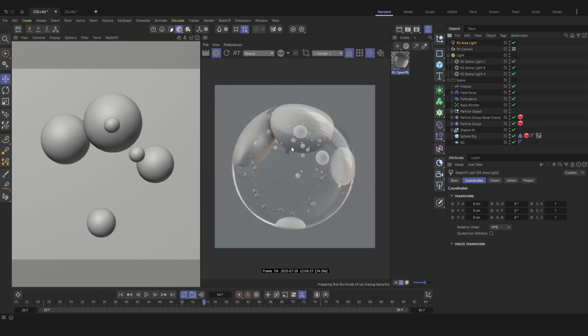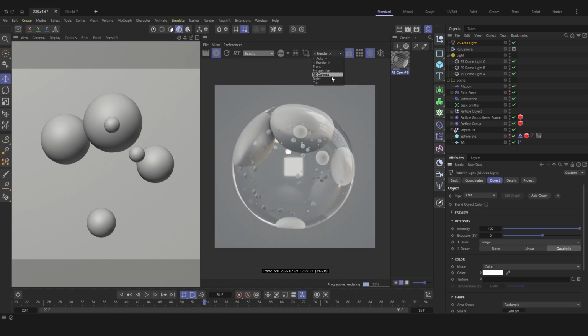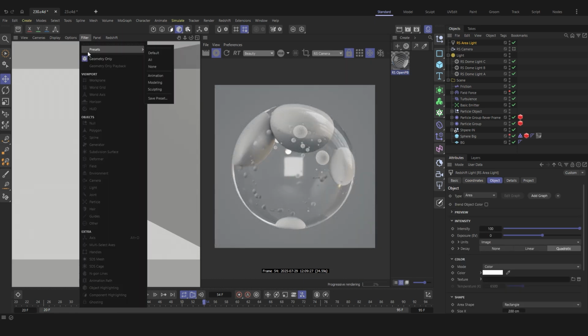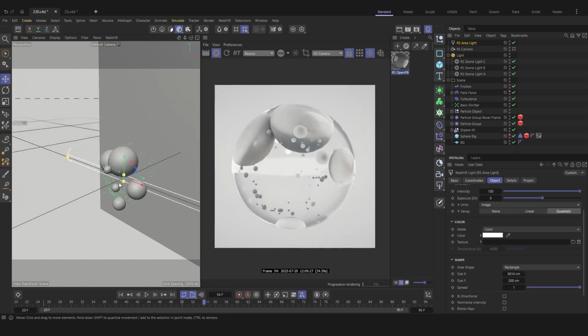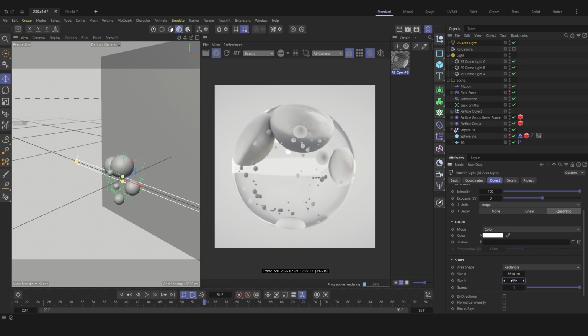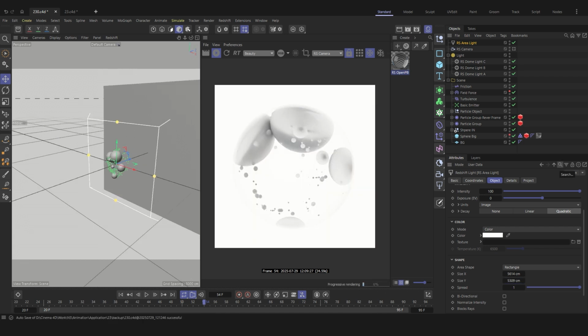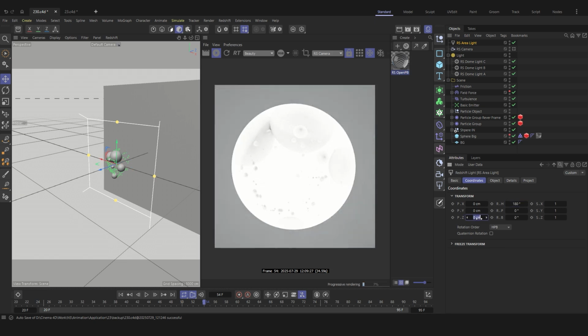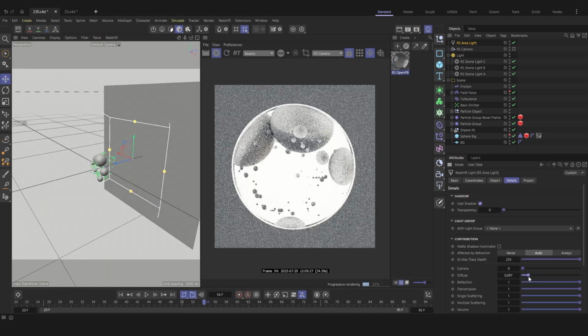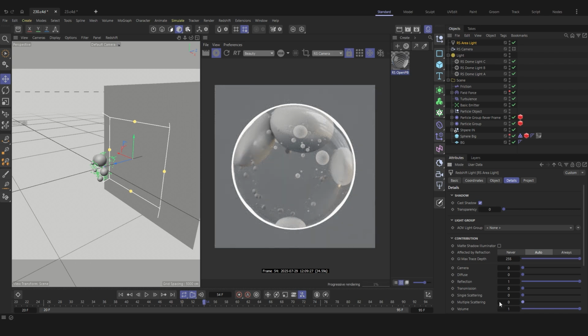Now let's add some lighting to create a backglow around the objects. But first, let's bring back the visibility of all scene elements. Our light source was too small, so we'll scale it up. I'll enter the same values I used in the original scene. To make it affect only the bright areas, we'll reduce everything else to 0 and keep only the reflection. As you can see, a glowing line appears around our object. Looks good.